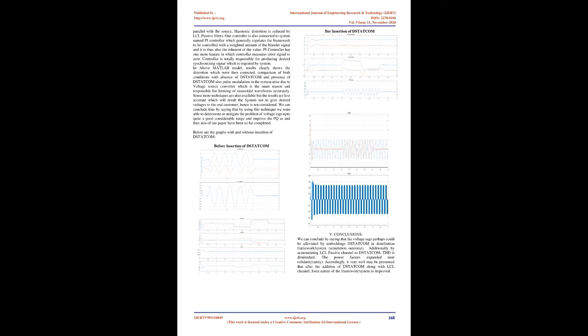See energy storage circuit. The DC source will be connected in parallel with the DC capacitor. Its work is to convey the input ripple current of this converter, and it is also the principal reactive energy storage element, accordingly storing energy for future use. It can either be charged by using a battery source or instead might be energized by the converter only.